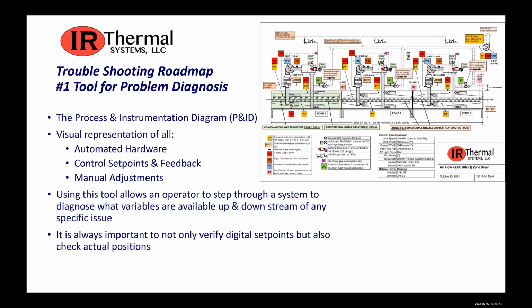It's always extremely important to not only check but also go out and visually inspect. Say I'm changing a damper, I want to visually inspect that in fact that damper is changing.